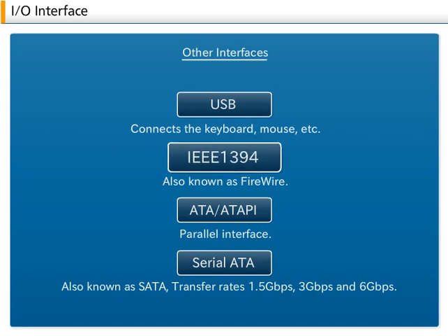Six, IEEE 1394. This was originally introduced for connecting to digital video cameras. It is also known as FireWire. Recently, products such as hard disks and DVD drives have been announced as supporting this interface. It supports transfer rates of 100 megabit per second, 200 megabit per second, 400 megabit per second, 800 megabit per second and even up to 3200 megabit per second, and as with USB, supports hot plugging.